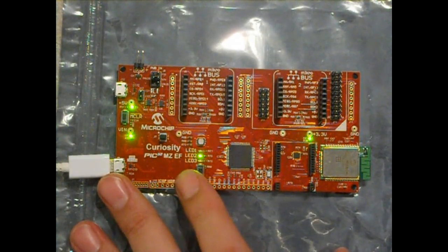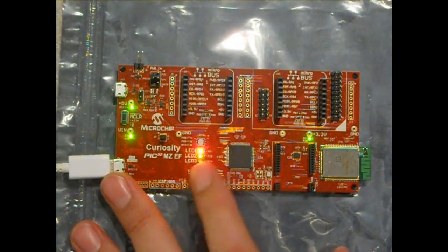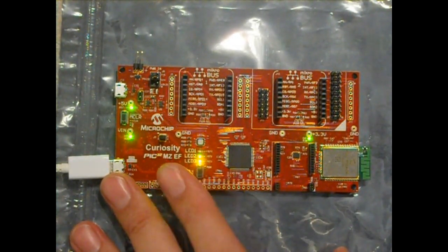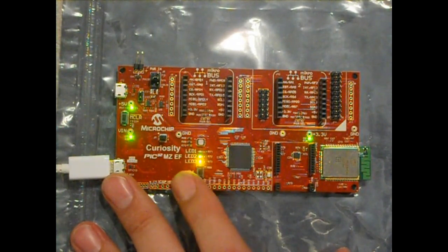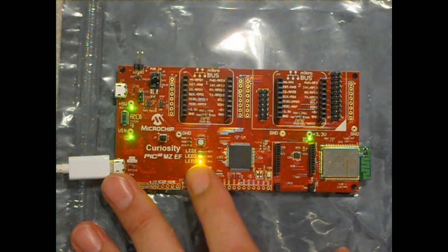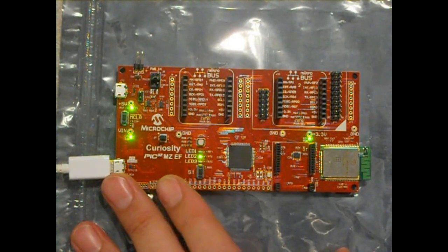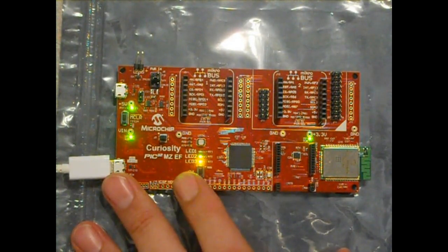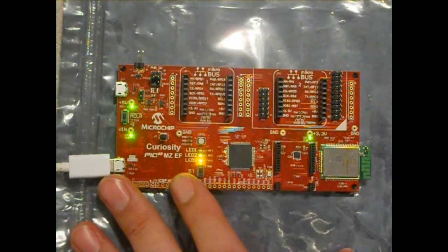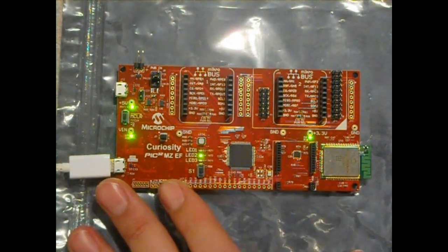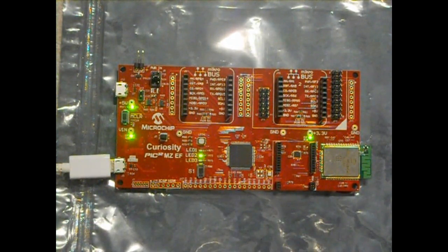So it won't necessarily toggle on and off like you want, because it's reading the switch so many times in a row. It's not just reading it once, it's reading it, like I said, 10,000, 100,000 times. And it's really whatever state it happens to be in when you lift your finger, that is what state it's going to stay in. Otherwise, it's going to go on, off, on, off, on, off, on, off, on. And if it stays on, then it's good, and it's doing what it's supposed to, but it's a 50% chance, essentially, that it's not going to do what it's supposed to. So I'm going to make a short video kind of showing that off.